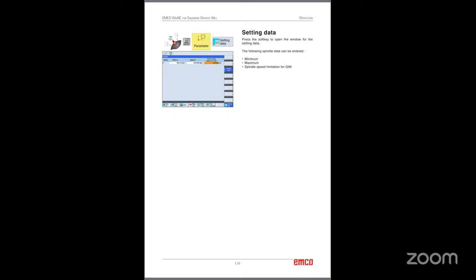Now I will give you a practical example. If I have a hole, R1 is equal to 50. In the program, I can write G0 X equal to R1. So the machine will take X is equal to 50. Later I will change R1 to 80. Then when the program executes G0 X equal to R1, the value will automatically change to 80.